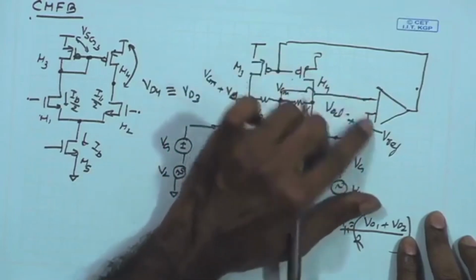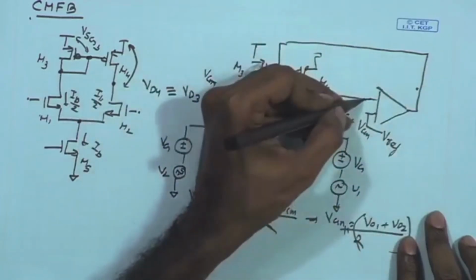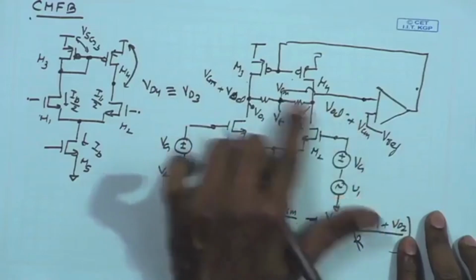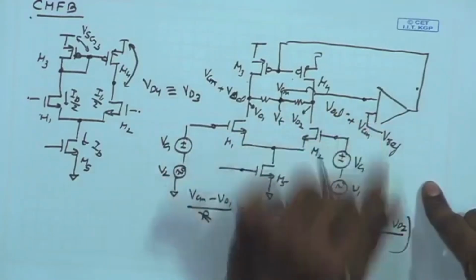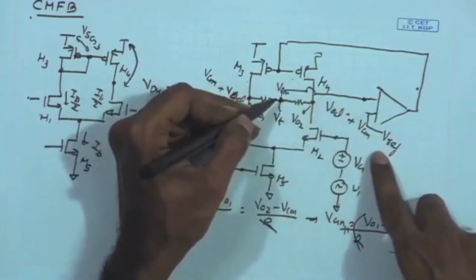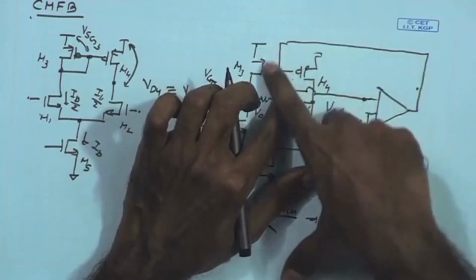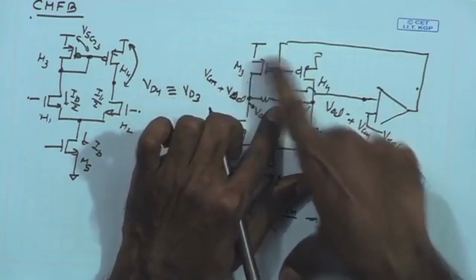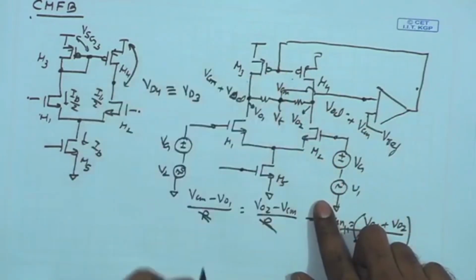It will make sure that these two voltages are same, and therefore, it will ensure that VCM is equal to Vref. And in order to make it negative feedback, I also need to make sure that the polarity of increase over here is causing the reverse action to be taken by the M4 and M3, which again tries to adjust this VCM back to the prior value.